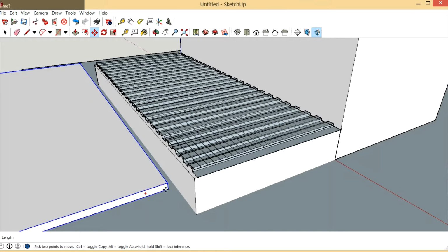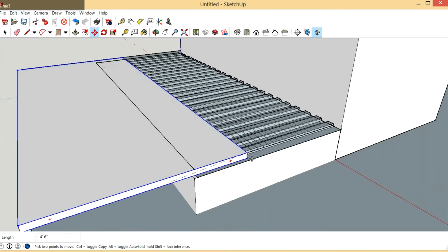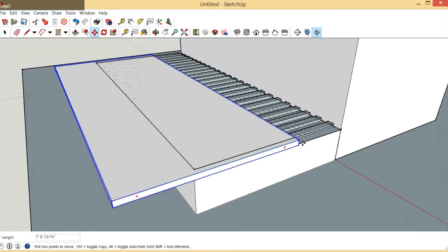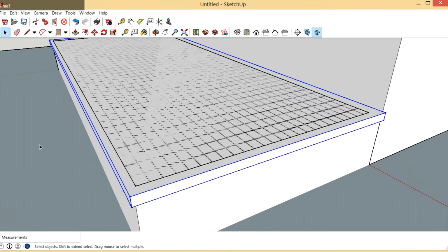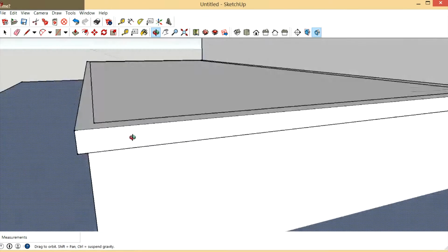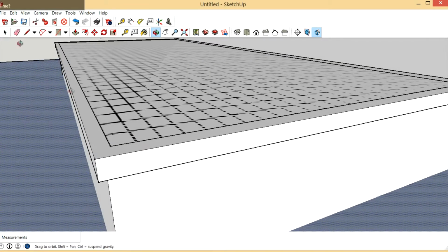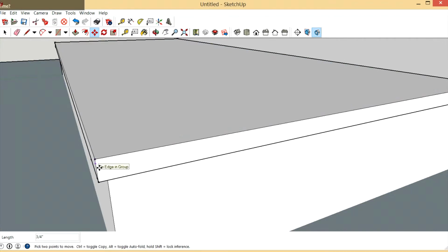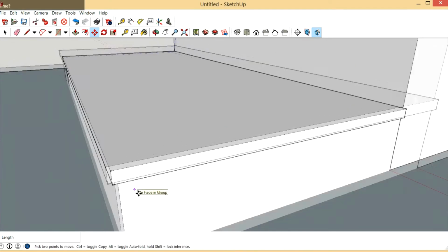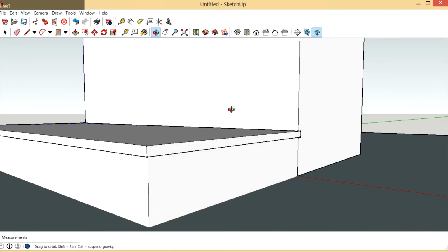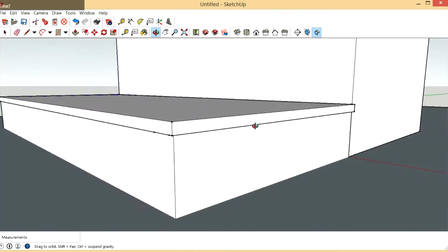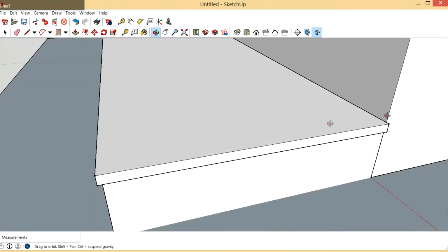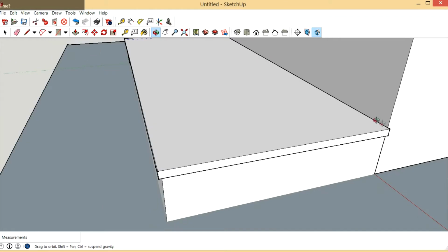So now let's take this concrete slab and put it back. There. And of course you can see now our wire mesh is kind of stuck up near the top. I'll lower it just a little bit. Move it down a 1/2 inch. So there you go. So without making this video 20 hours long, let's see, how can I jump ahead to the next important thing, which would be how we flash along this wall.